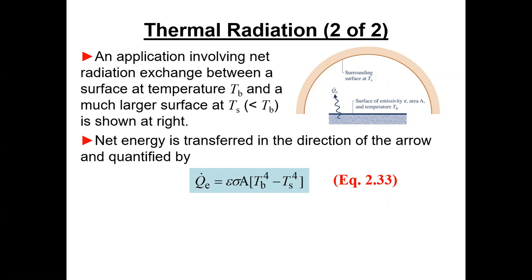What if that thing was only half? Instead of being 180 degrees, it was only 90 degrees. Then part of what that slab would see would be that dome, and the other part of what it would see would be whatever's on the other side. And now whatever's on the other side is going to have a different temperature most likely. So see, it gets complicated. You have to do a net exchange between that slab and everything that it sees. So there is a view factor here, but this is conveniently contrived so that the view factor is 1.